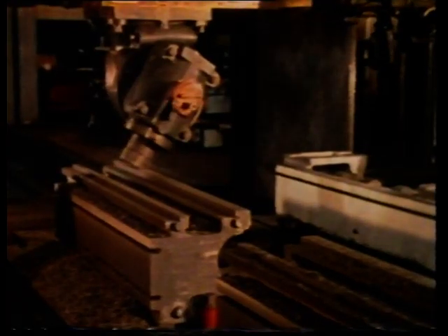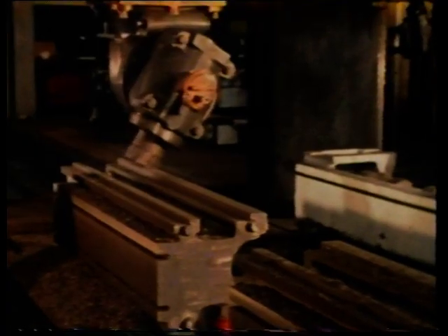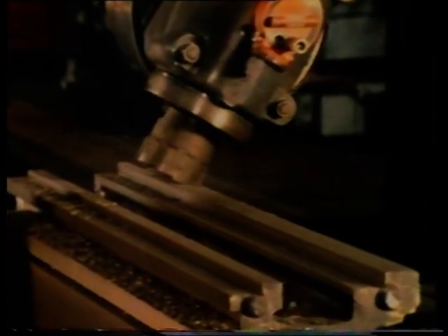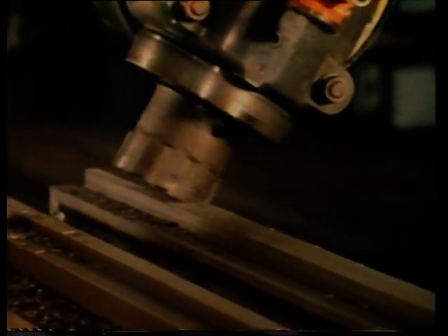These castings are made of one such material. They're lathe beds. In this cast state, material is relatively soft and easily machinable, so the large quantities of unwanted material can be removed by milling. Here we're machining one of the slideways. Now, in service, this part needs to resist wear and indentation. It must be hard, but in its present state, it's relatively soft, so now the slideway must be hardened.